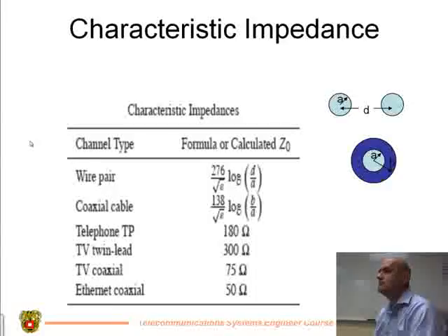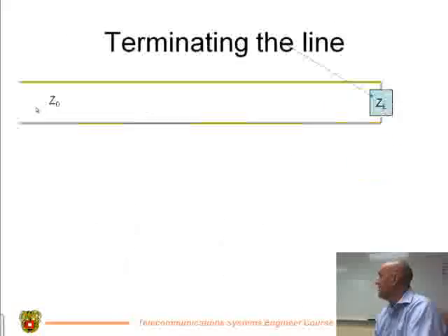Maybe I'm missing something. So why are you saying that it affects it? Because of the fact that impedance changes with frequency? Right. Well, because what happens is if you don't match it up just right, then you're going to bounce between an antenna and the device that's connected to the other end. And now it does start to depend on the length of the cable. If it's a quarter wavelength or a half wavelength, things are going to be different. We can do little quarter wave matching stubs and all sorts of weird little things that I'll show you today and tomorrow. Yeah, that's what we're coming to right now. Foreshadowing. Got it. Right.